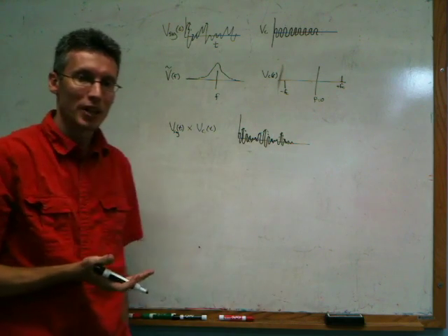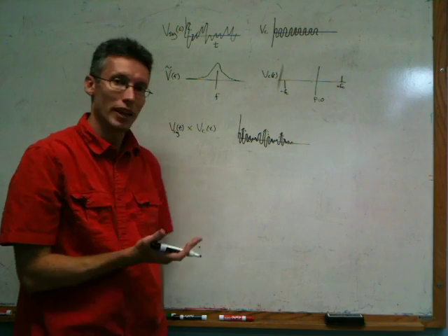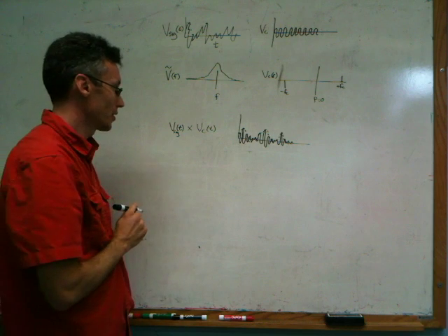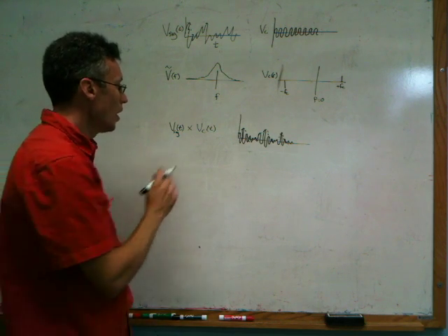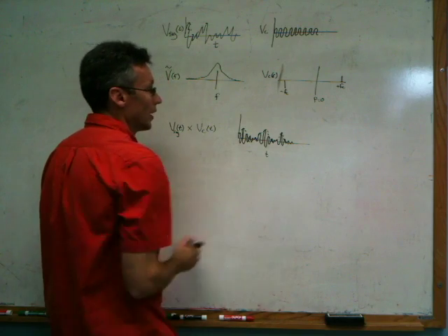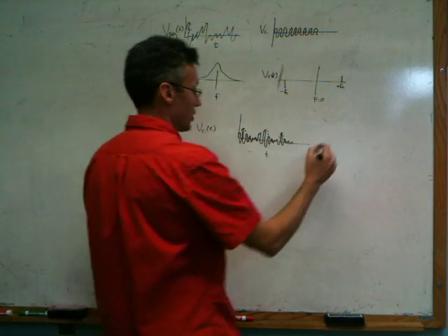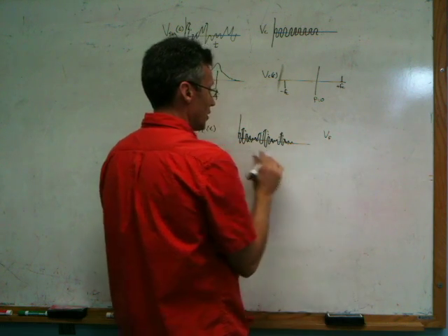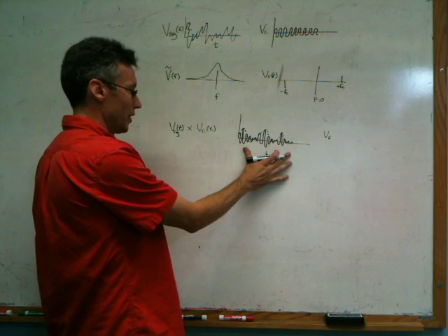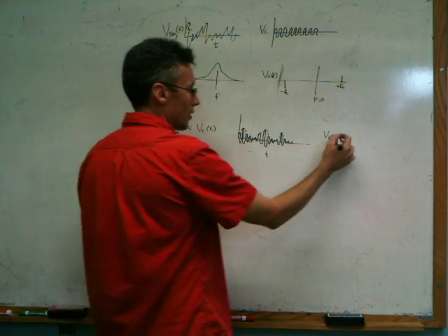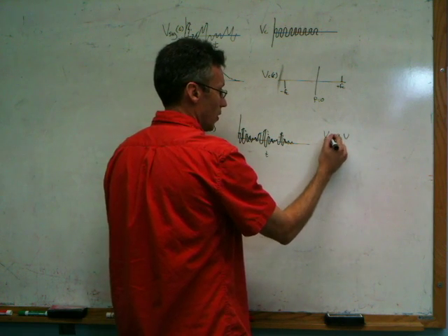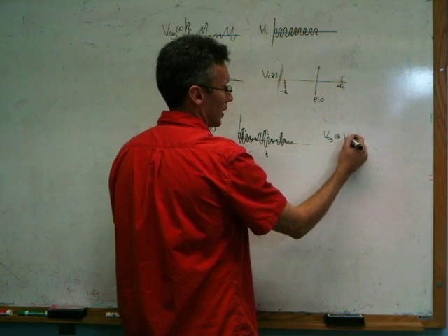And the ideas that we're presenting here, we'll look at amplitude modulation, but they're very similar for frequency or phase modulation as well. Okay, so this is the time domain. That's not the most useful representation. If instead we look at the Fourier transform of this, the spectrum of this, that's going to be the convolution of my signal and my carrier.